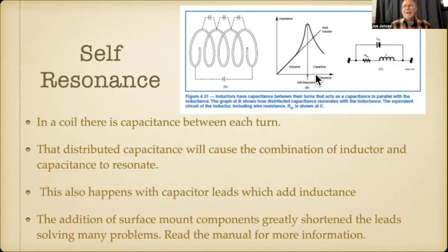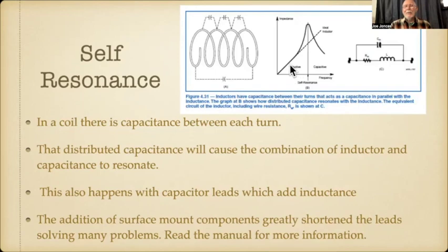If you look at this scale here, down in this area here, that inductor will work just fine. With any capacitor, you don't have to worry about anything. But if you approach its self-resonance, this is what happens. It goes through this and makes all kinds of trouble.